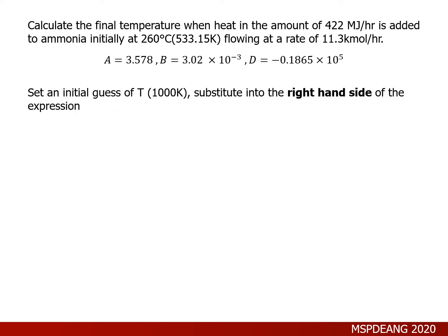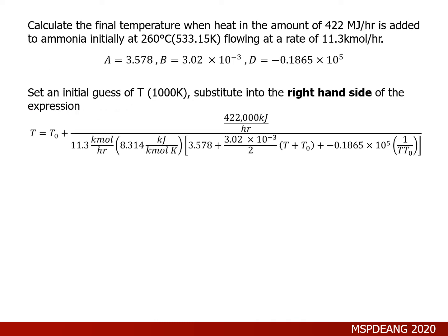To illustrate this, this is our working expression from earlier, with the necessary values already substituted. Take note that I converted Q into kilojoules per hour to keep our units consistent. For all energy, make sure the units are consistent: kilojoules, N in kilomoles, and our gas constant in kilojoules per kilomole. The temperature should always be in Kelvin when evaluating the integral.